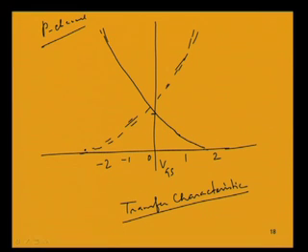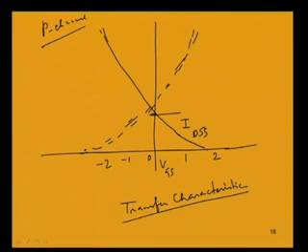So, this gives you the IDSS. So, the transfer characteristic for a p channel type MOSFET, even for enhancement type or depletion type, will be just a flipped version to the left, or it will be just bending towards left of what was obtained for the n channel type.